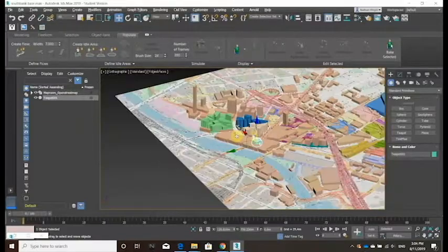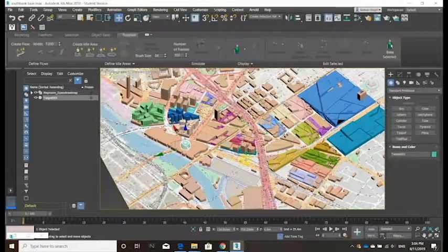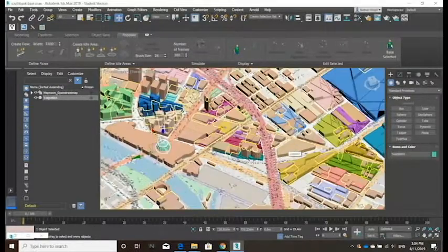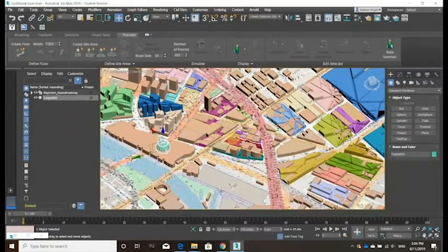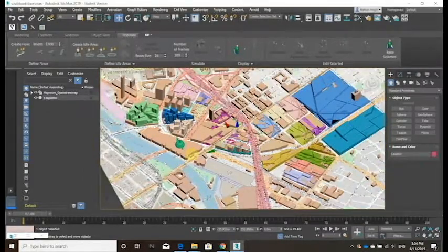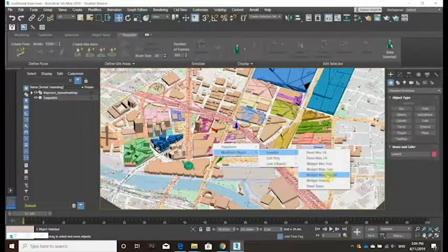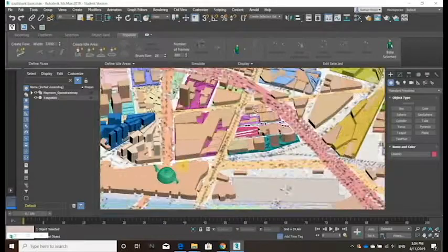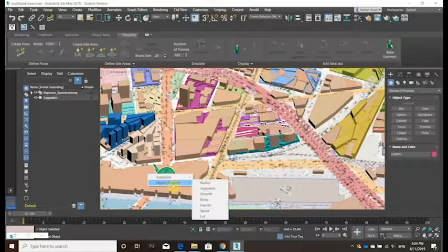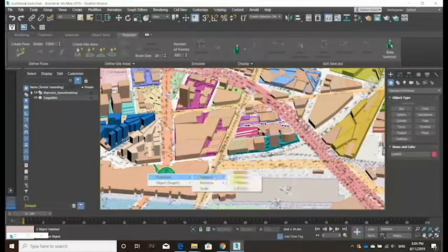Alright, so if we want to change some other density, like growth densities, we can do the ones we did before. So this one was another group of ones we did. So we're going to right click that one, wire parameters, modified objects, greeble, and that was again with the widgets. So widget max height, and then I will click onto the teapot and do transform position, X position.